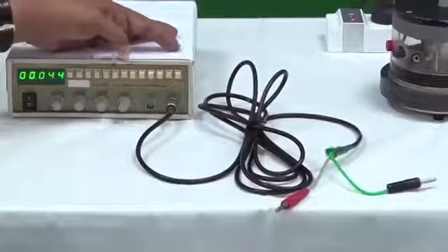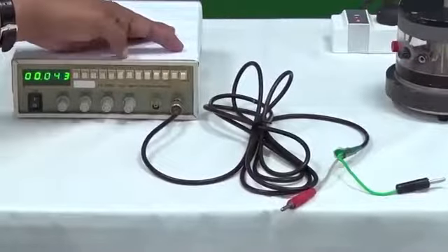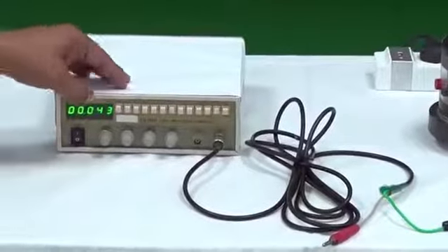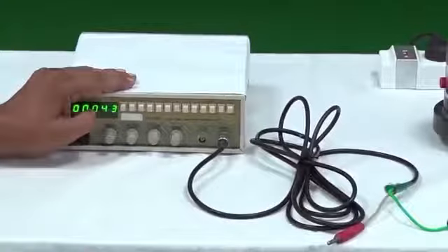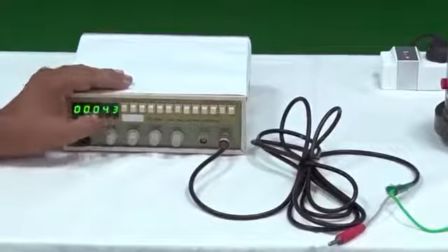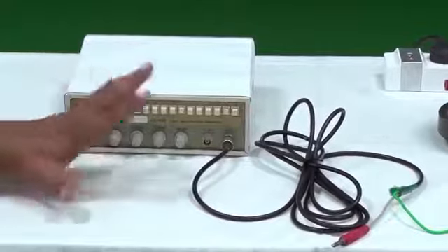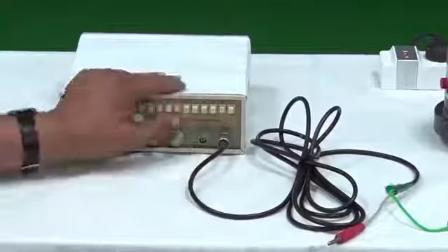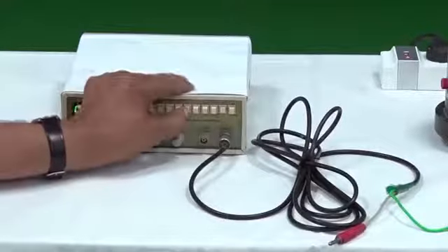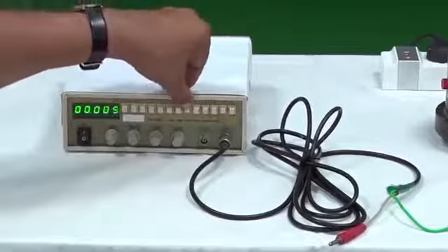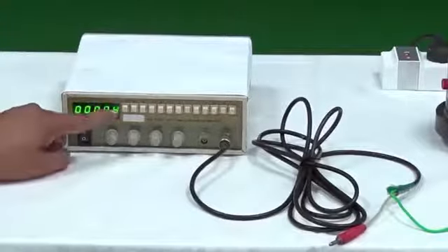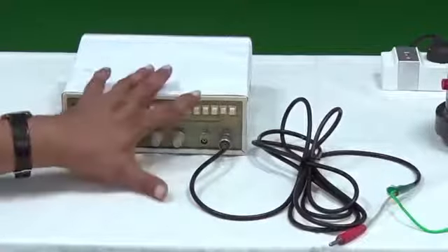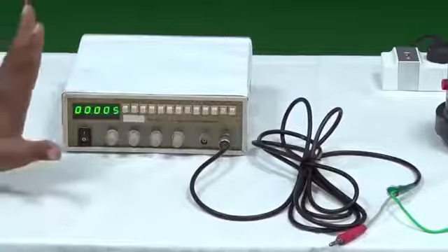The frequency can be selected, the various ranges are here. So, this is at the range of 100. Actually this time the frequency is 43 point something. So, it is showing 43 or 44 like that. So, that much is the frequency, 43 hertz. I can change the units, and if I press this particular button, I had selected another range, and this time it is 4 point something hertz. So, it is producing AC of 4.5 hertz or 5 hertz.